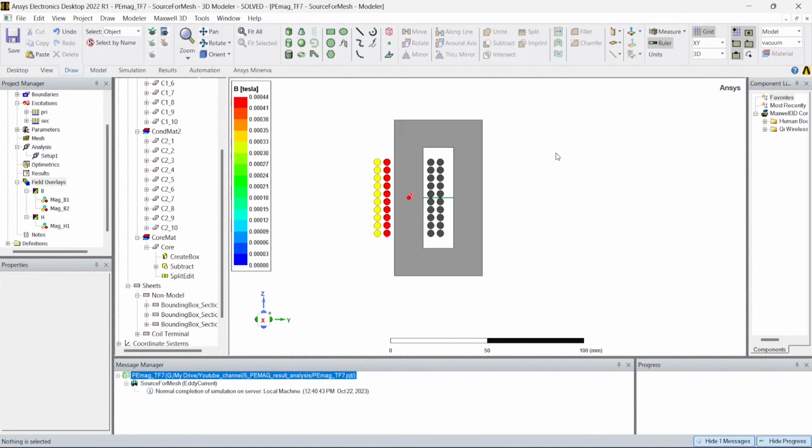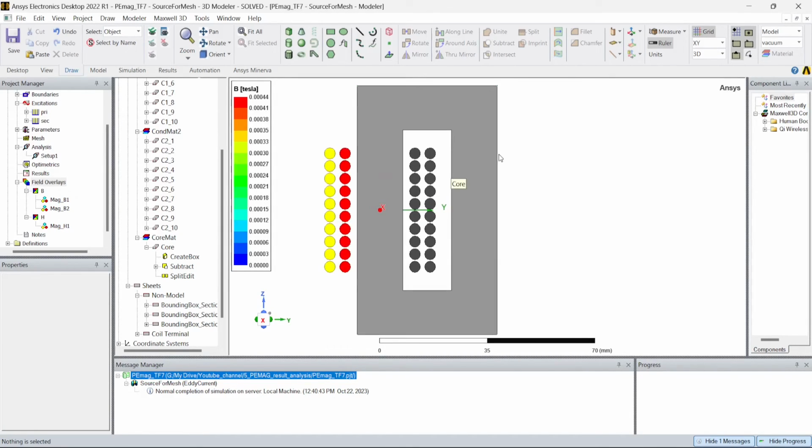Now for the starting, this is just okay. We got our leakage inductances, magnetizing inductances with that target error. To go into a more detailed or more accurate solution, we can make that criteria more stringent. So for now, this is just okay.